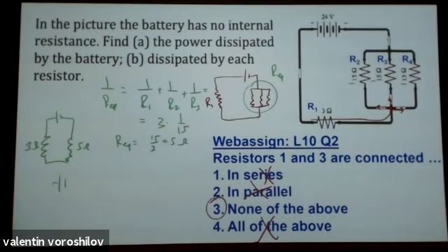All right. In my mind, what did I do? I combine these two in one, and now I have everything I need. The simplest circuit, electric current will be equal to 24 over 8, 3 amps. And this electric current travels where? It's important. It travels through the battery, it travels through this resistor, it travels through this equivalent resistor.